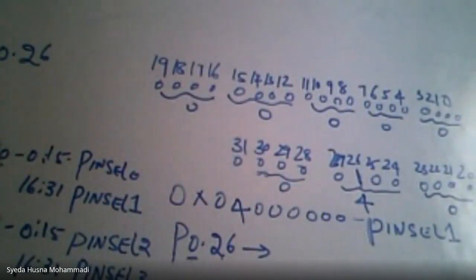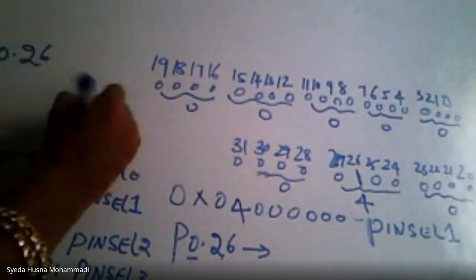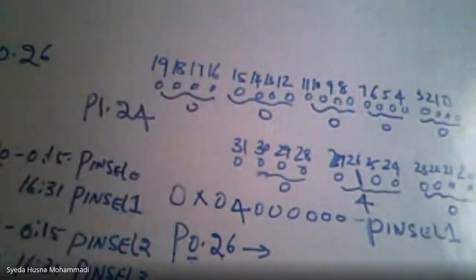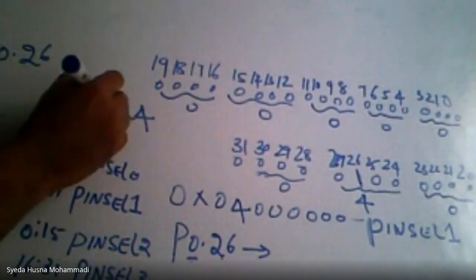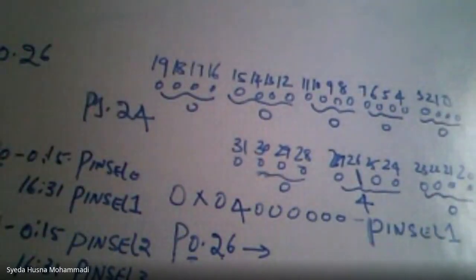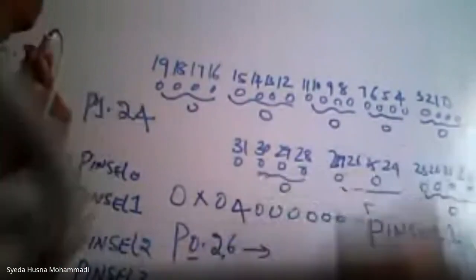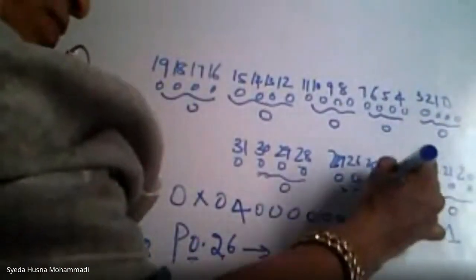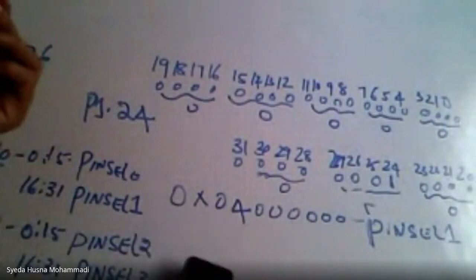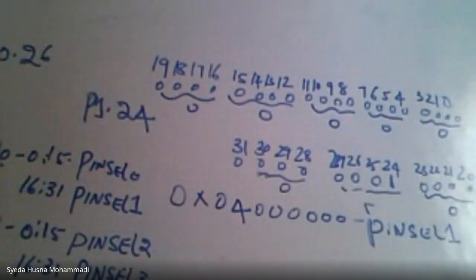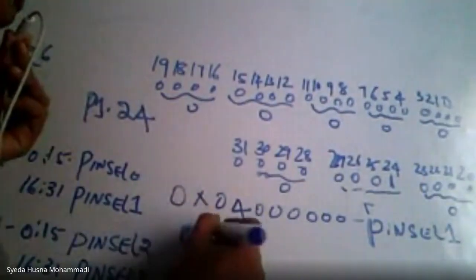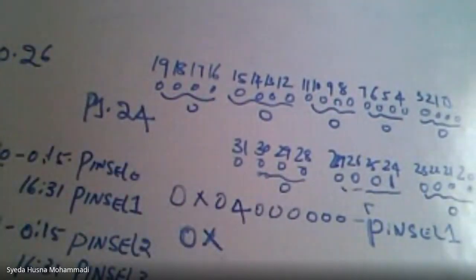On similar lines, now I have connected my DC motor onto the kit. It is connected to port 1 pin number 24. So I have to configure this DC motor in the direction of output. Please go to pin number 24 and configure it as 1. The rest of the bit values will be 0. So come on, what is the address you'll be generating?